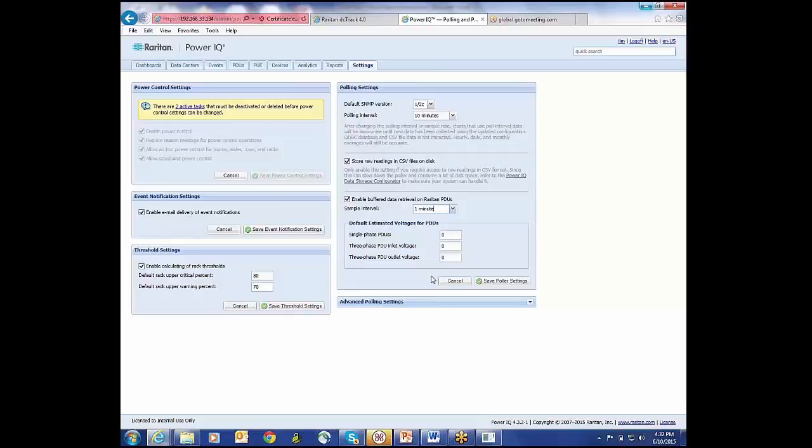This configuration is network friendly and resilient because the solution will only go out every 10 minutes to collect these 10 1-minute samples. But also, if the network is down for an hour, no worry. The next time the solution connects to the device, it'll pull all of the readings from memory. And in this particular configuration, with 1-minute samples, it has the ability to store 2 hours worth of readings. If I want longer storage, I can increase the sample rate, and if I made the sample rate 10 minutes, it could store 20 hours worth of data.